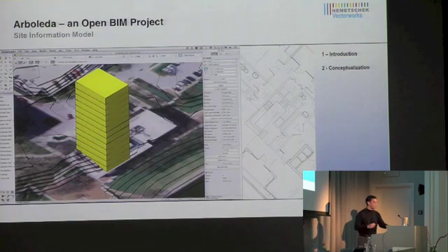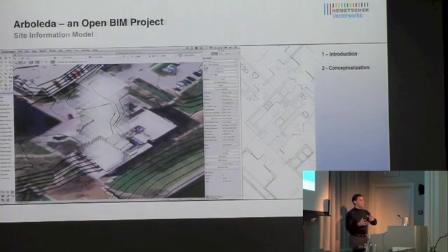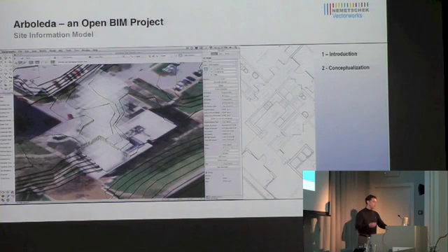I had to make decisions, and I wasn't sure if the building needed to be higher above ground, underground, or somewhere in the middle, because I have parking lots. So by combining my mass model and my site model, you get what? First numbers, cut and fill calculations, how much dirt I need to dig, or maybe not. So that's one of the first pieces of information by using a 3D model.